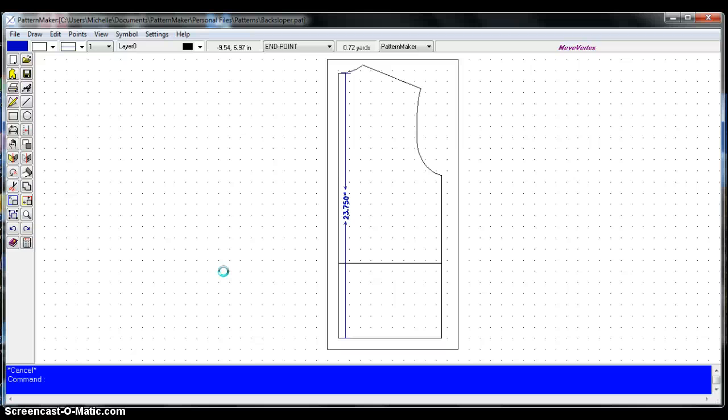We find my place again. There we go. If you wish, experiment with different numbers in the other fields for changing your dim size to see what effect they have on the dimension line. Arrow size and line offset are not covered in this tutorial.